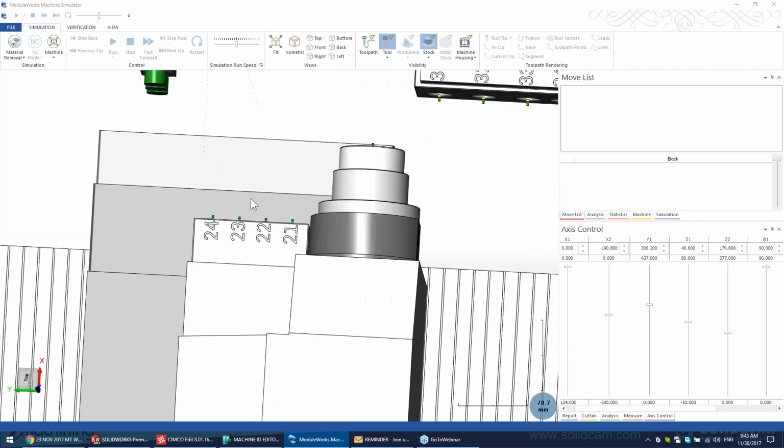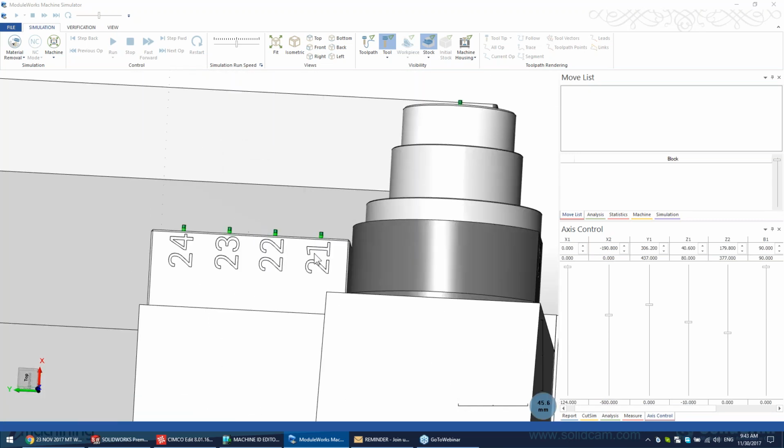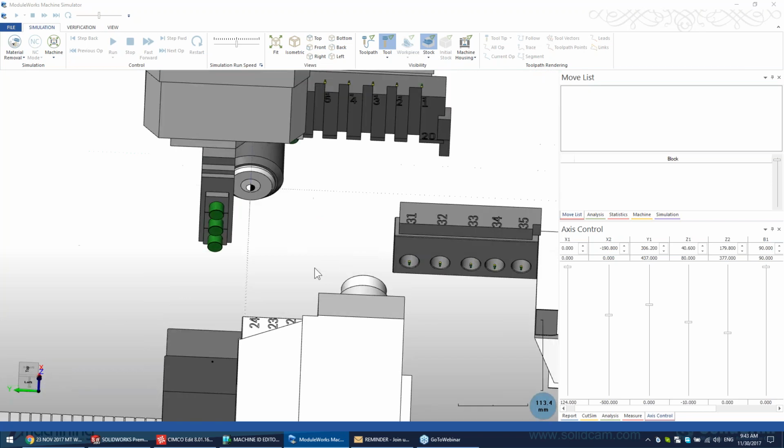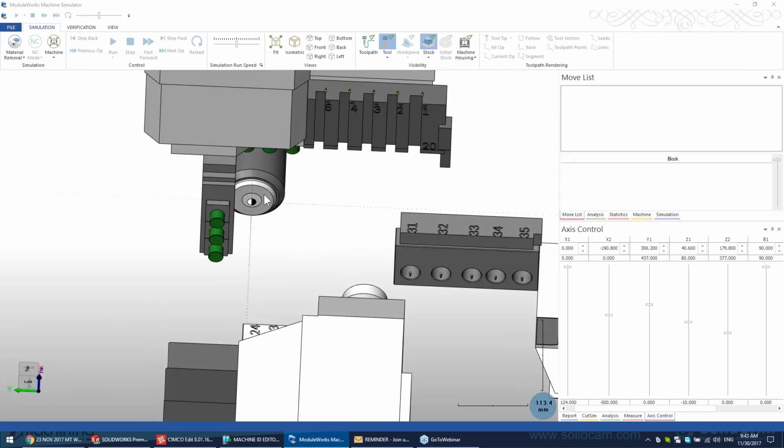Here I will work milling with one of the 21 to 24 stations on the main spindle. Milling on main spindle is a combination of axes and tools. One station from 21 to 23, a milling tool working on the main spindle. I will use X2, Z1, and C1.